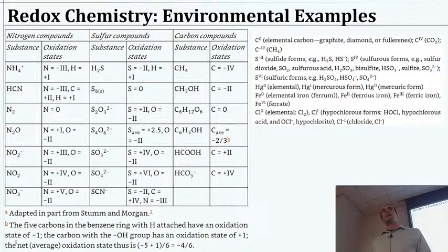Well, how many electrons does it take? How many chlorine molecules do we have to consume in order to achieve that? A very common example would be if we are treating water that has sulfide in it. Perhaps we're taking it from groundwater and we're adding chlorine. Some of the chlorine will react immediately with the sulfide, and the oxidation power will be spent.